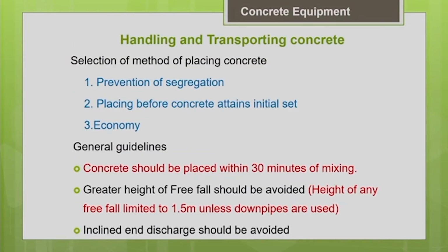Very commonly you can see that people put a lot of effort into the mix design of concrete and the preparation of concrete, but very often they do not care much about the method of transporting the concrete. If you do not carefully transport the concrete to the desired place, during the transit the concrete may get segregated. If segregation occurs, you will not get a homogeneous microstructure in the concrete, and that is going to affect the strength and durability of your concrete. So, that is why we need to put proper effort into selecting an appropriate method for transporting the concrete.